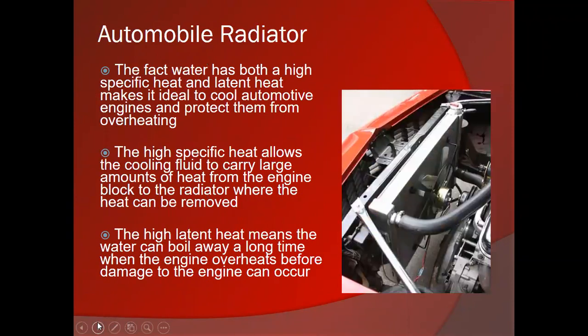As we heat water up, we can use this to actually cool different systems. In the science building, we have a chiller on the roof, and what the chiller does on the roof is it sprays a mist of water, turning the water from a liquid into a vapor.